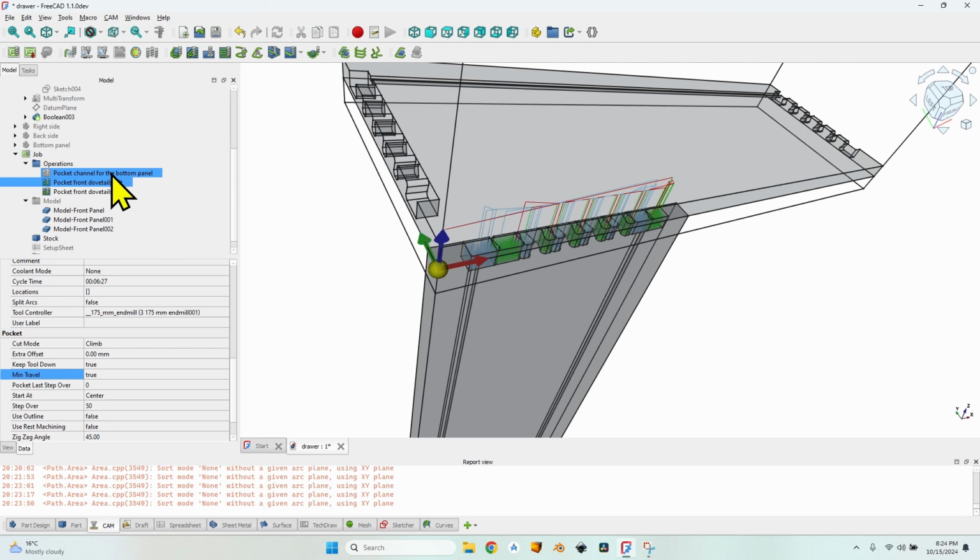Whenever using this kind of approach for some projects, I would suggest after each modification, after modifying the drawer, when you want to go to the CNC, turn on the visibility for all the jobs, for all the objects, for the operations, and make sure everything is okay.